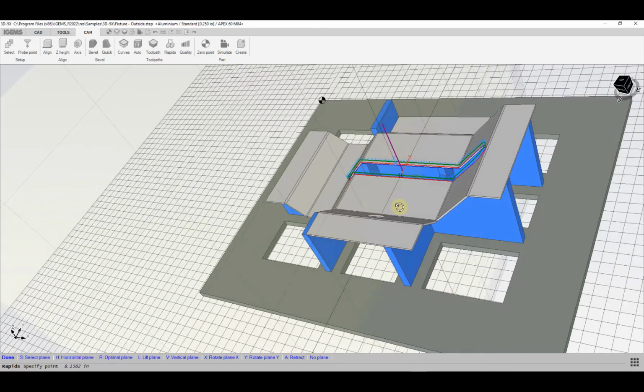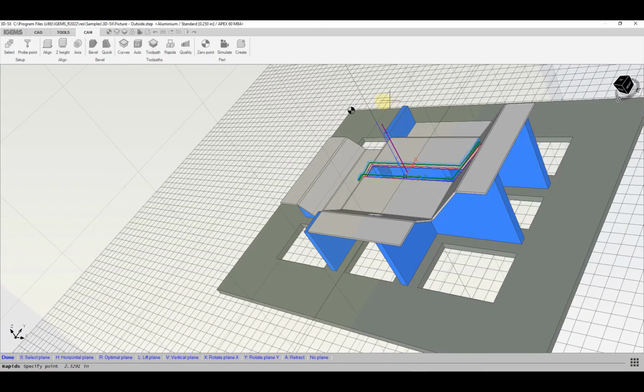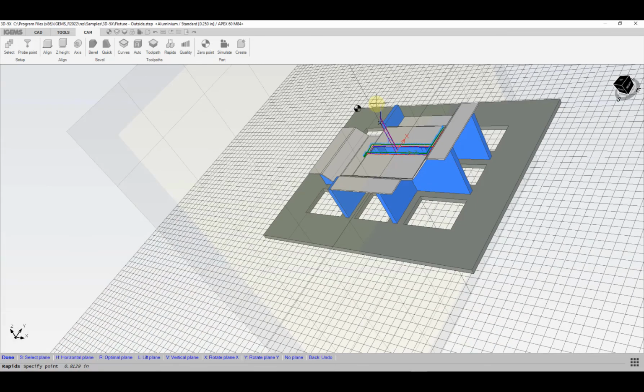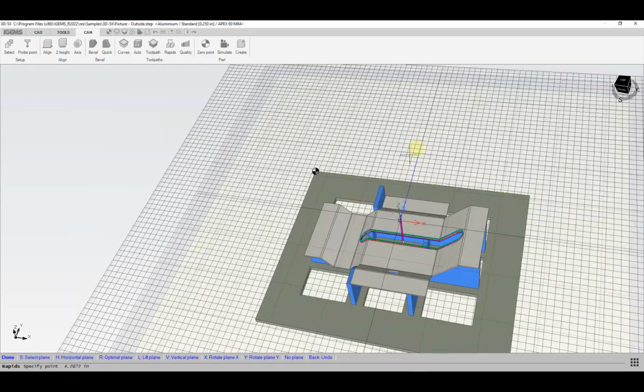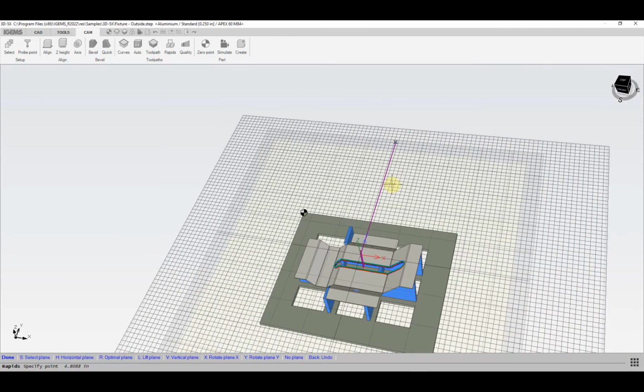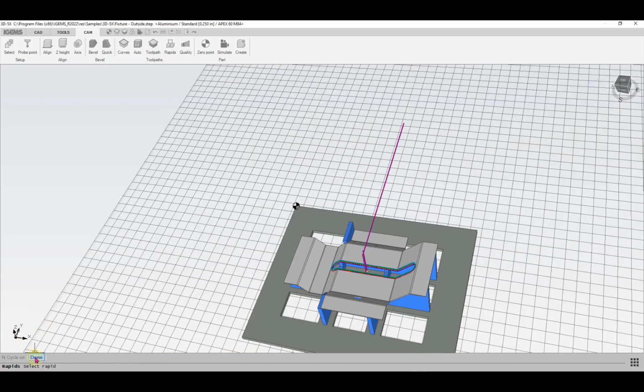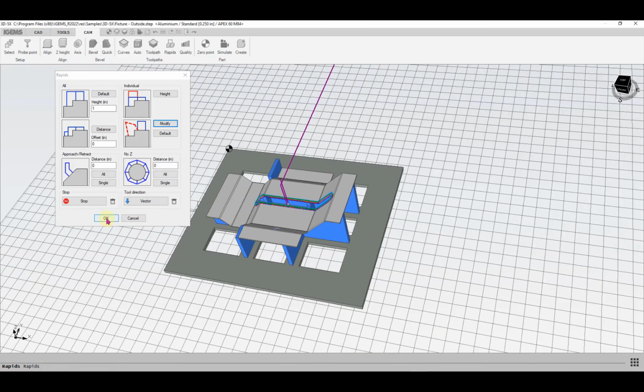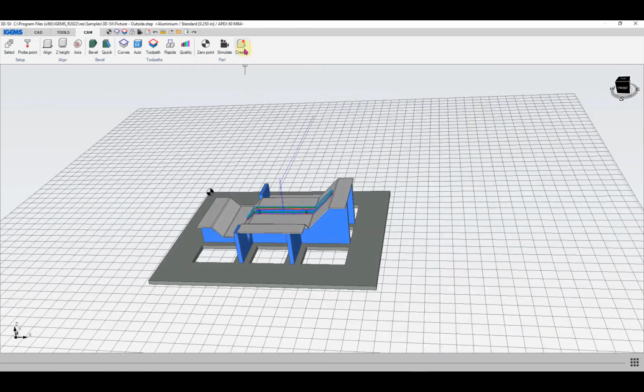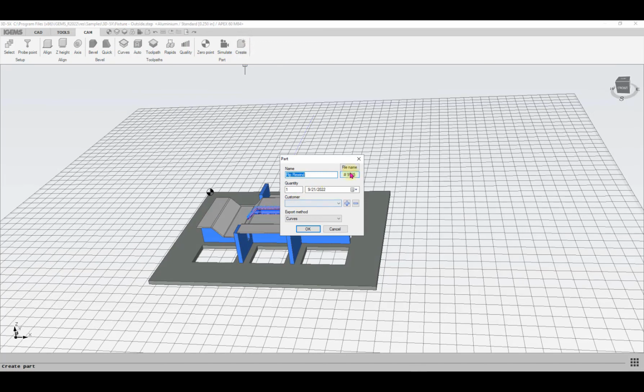and turn on my ortho. So if I wanted to lift up, say, 2 inches, and then go to horizontal plane, and I want to go back 12 inches or something, get well out of the way, hit enter and done, and then click on OK and create parts.